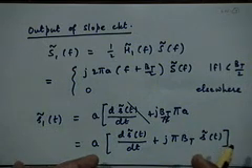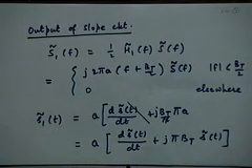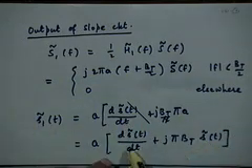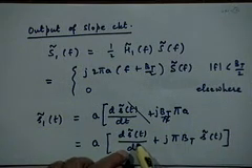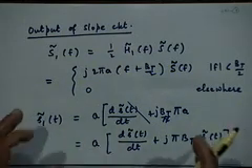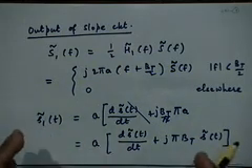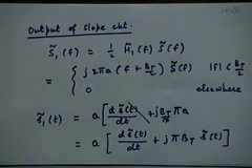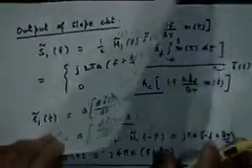If the input signal does not have a constant amplitude and has a time varying envelope of its own, then those variations will get passed on to the output, which we do not want. So, the balanced discriminator that we have discussed so far is sensitive to amplitude variations of the input signal. That is something that you must appreciate.